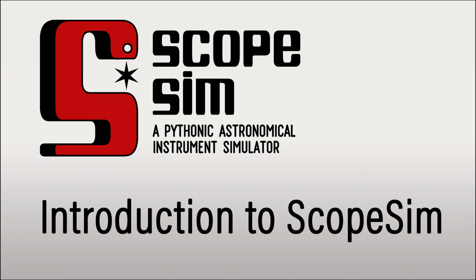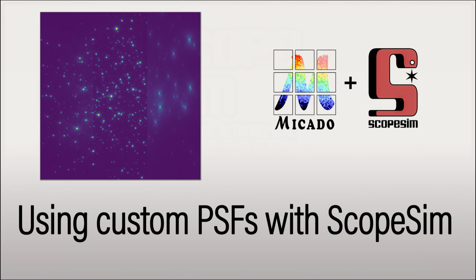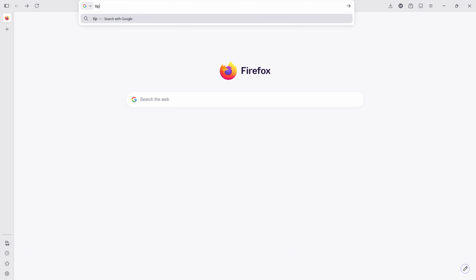ScopeSim includes built-in point spread function models as part of its instrument packages. If you want to use a custom PSF instead, TipTop provides a straightforward way to generate one. In this tutorial, we'll generate 2 point spread functions with different observing conditions and use them directly in a ScopeSim simulation. We'll begin by opening TipTop in our browser.